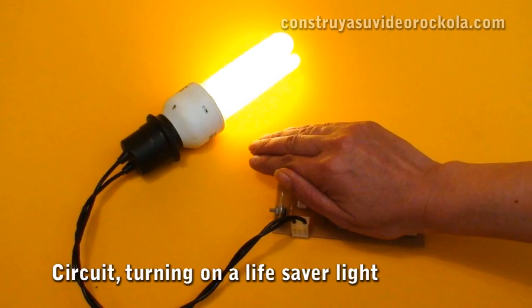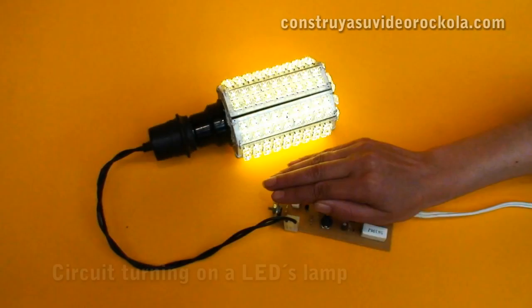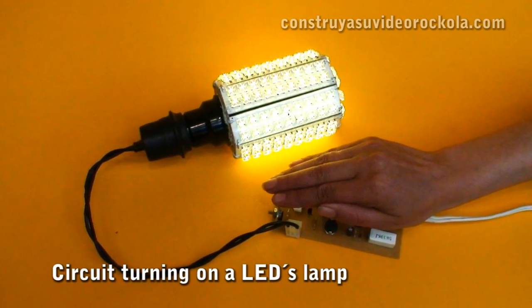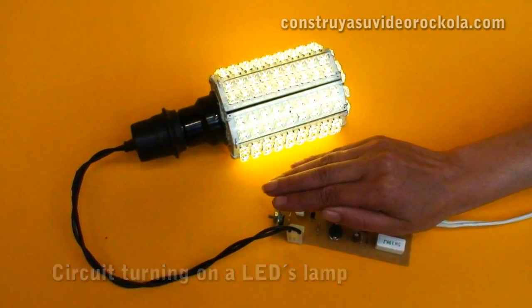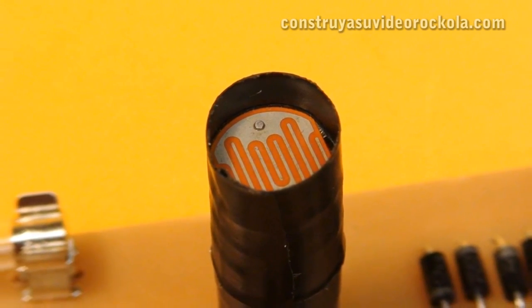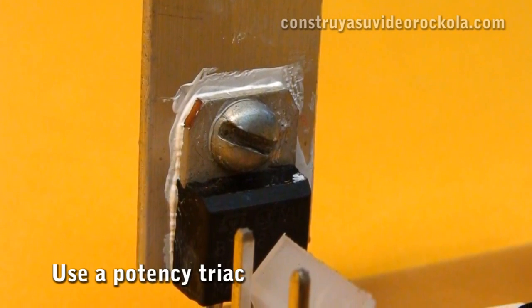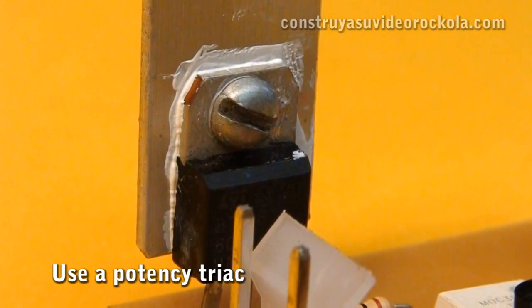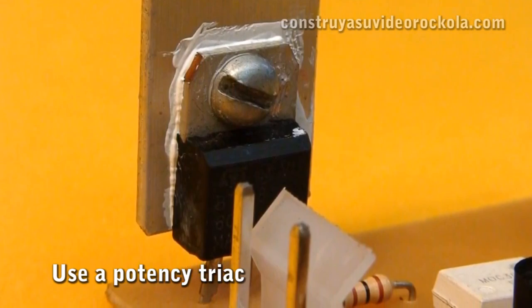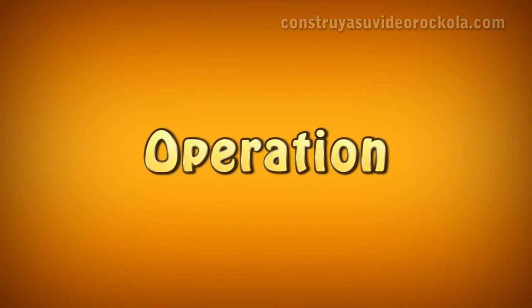This circuit operates with voltage from 115 to 220 volts, no need to make any changes. You can light a bulb up to 100 watts. If you want to power higher wattage lighting devices, you should only change the BT136 triac for one that supports more amps, such as the BTA08-600, which supports up to 8 amps. Operation.